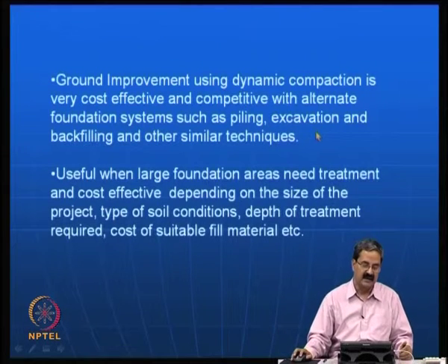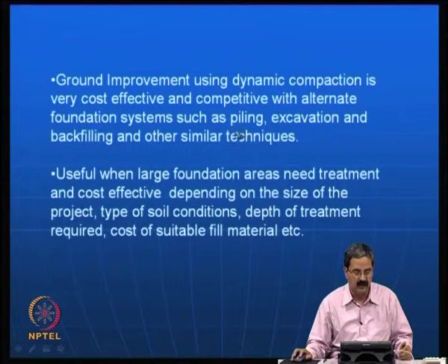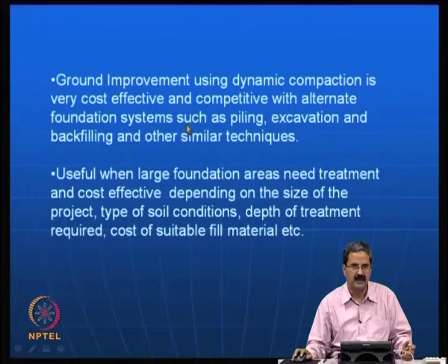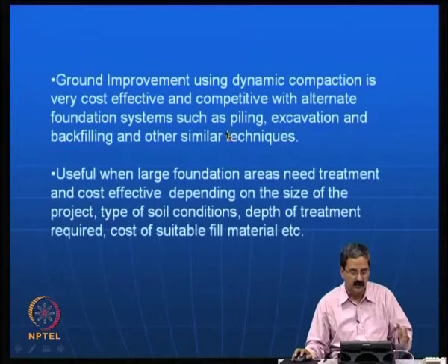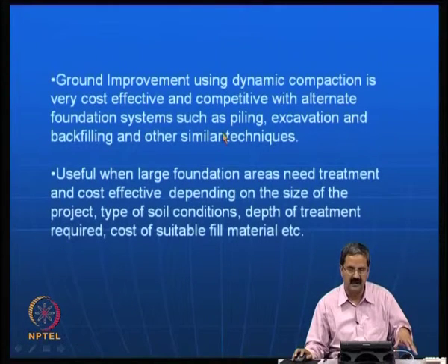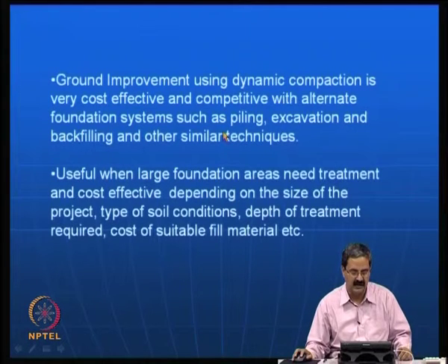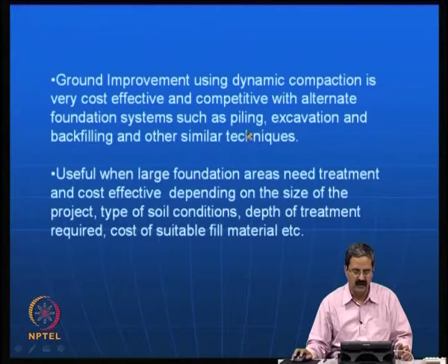So, in this case the technique was very effective and cost effective. In fact, it is maybe 40% cheaper or even 50-60%, because piles are expensive, compared to just tamping that you are trying to use and doing SPT tests and all that. Definitely what we are trying to do is that we are trying to improve the soil as it is, rather than trying to remove the soil and then put in an RCC and put some piles and all that, which is efficient in terms of the efficiency.